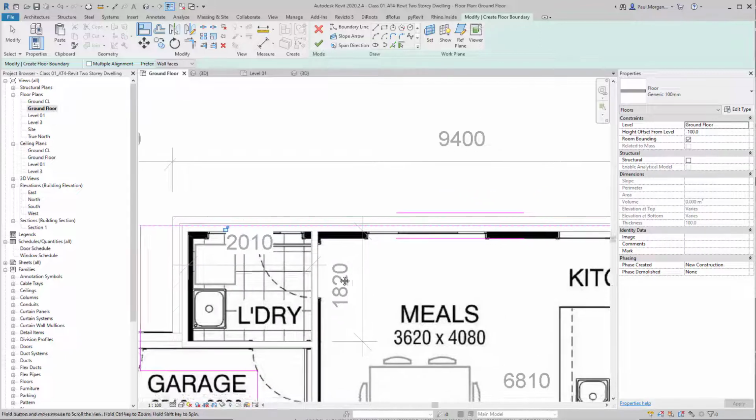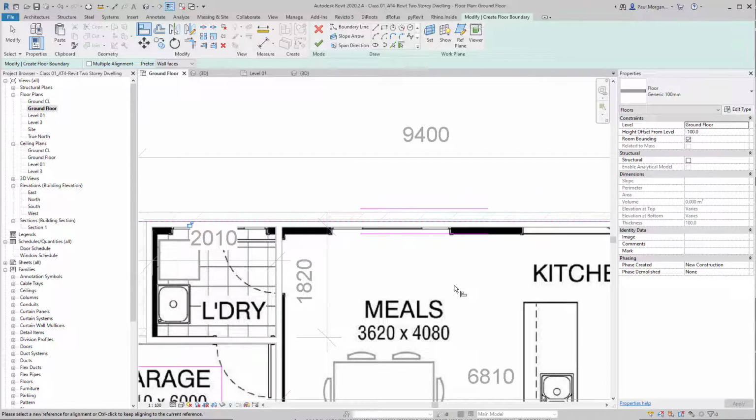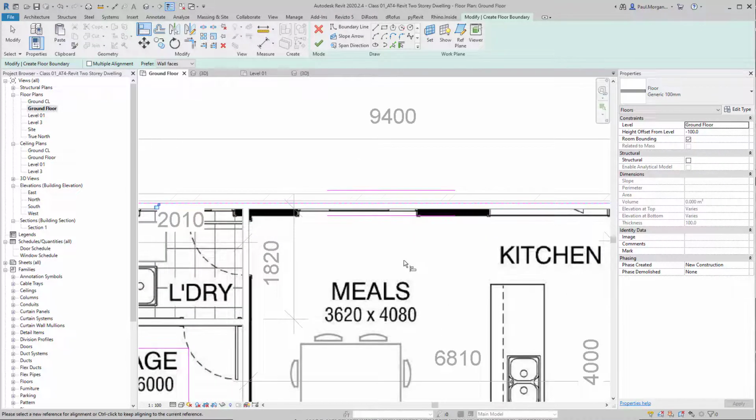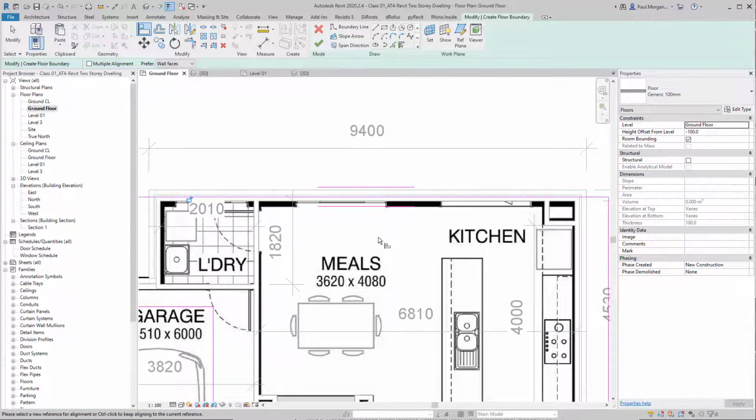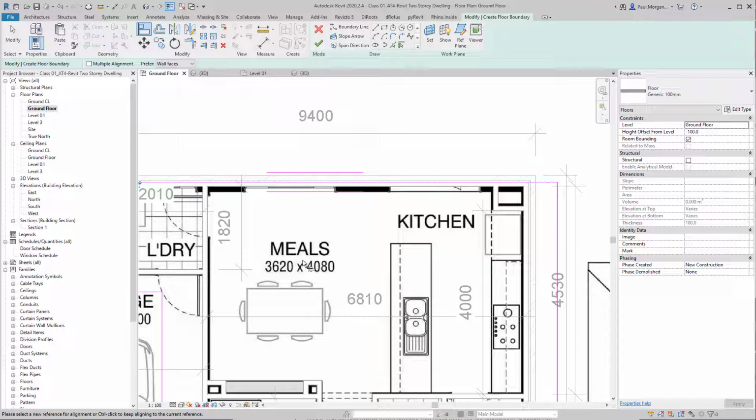The other thing too is if you don't keep track of which items are padlocked and which are not, you might be working in a team and you might go move a wall and you'll get a ton of errors that appear saying items are breaking, they can't join, things will be deleted, views will be stuffed, and it can be a really tricky tool to organize. So I'll be honest, I rarely see it used even in large practice, even on very large buildings, because it's just easier to not have that many warnings and errors that appear.